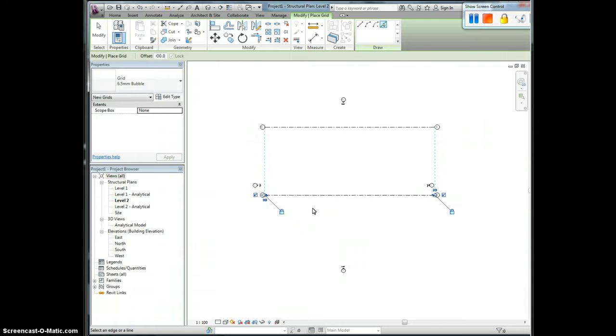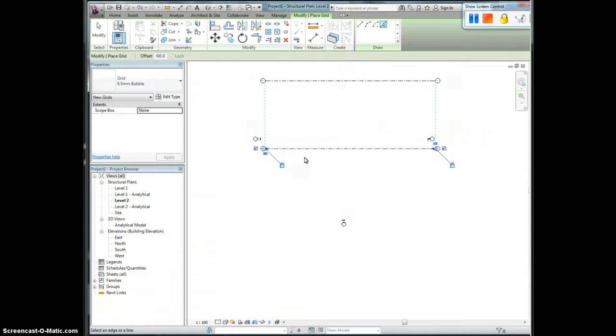Okay, of course the next thing to do is just continue. But I want to caution you. Now, please be careful. When you approach this line, put the cursor here at this end, the parallel line of the next grid line will be drawn below. If you are pointing to this from top, picking up this line from top, your grid line will be drawn on top of this line. And that is going to be dangerous because on top is line 1. If I'm not careful, I make a mistake.